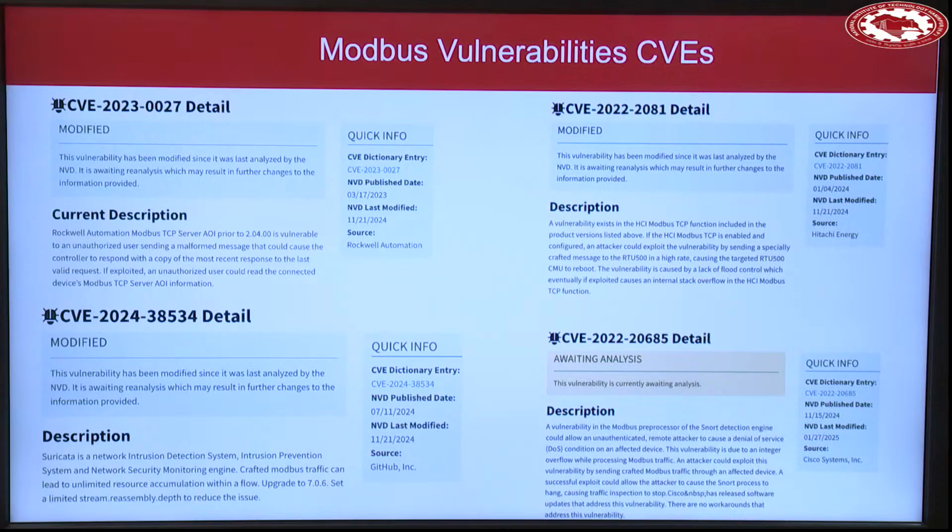And how do you derive this? Have you accessed CVE, by the way, on the web? If you Google CVE, you get to a website. It's a CVE dataset. There, if you type Modbus vulnerability, you get a list of them. So these were the possible vulnerabilities that have been identified on Modbus. So you get to know what the issues are. As an attacker, you need to exploit one of those in order to get into the system.